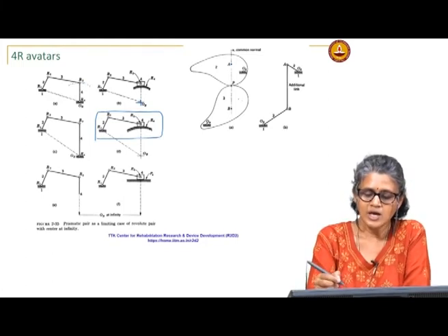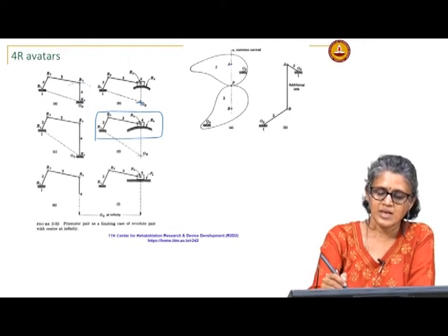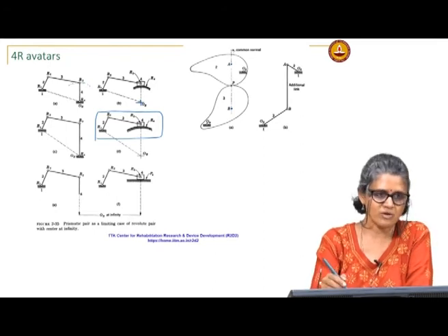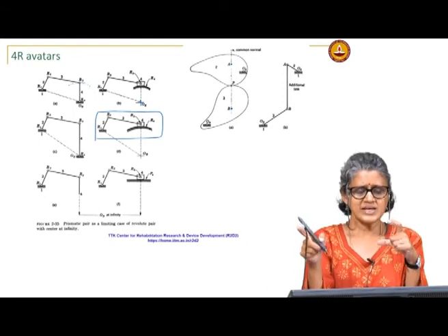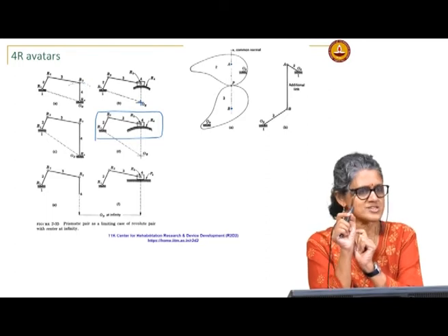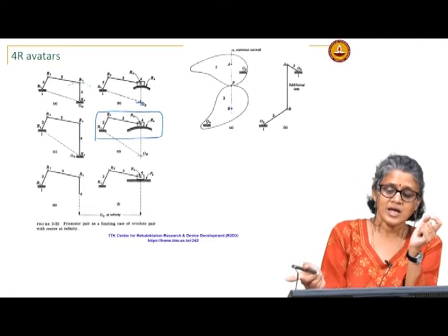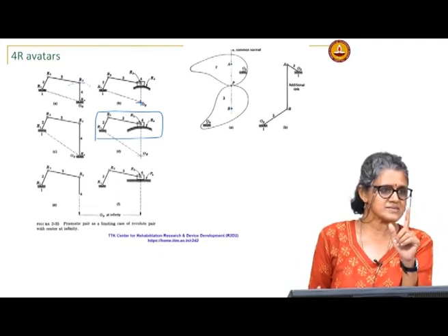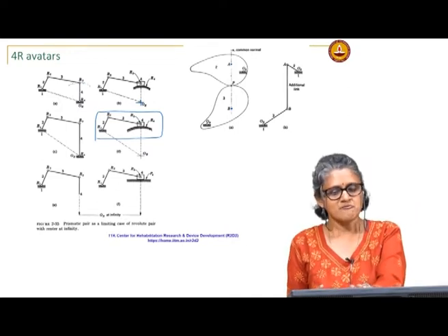Okay. Now, the property of the center of curvature is such that the common normal at the point of contact will obviously pass through the centers of curvature. The centers of curvature do not change for 3 infinitesimal positions. Okay, that is a property of the center of curvature. And so, using that we can say that the velocities and accelerations of this mechanism will be equivalent.